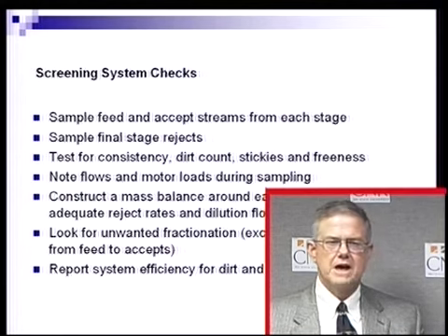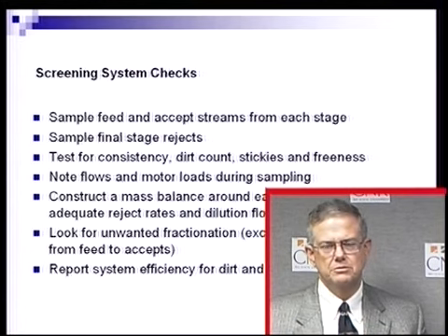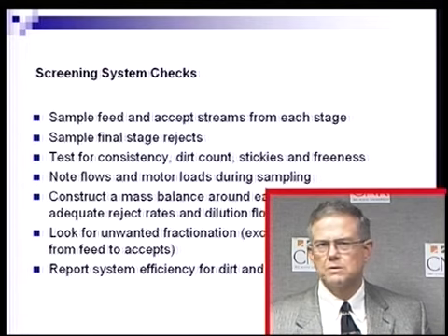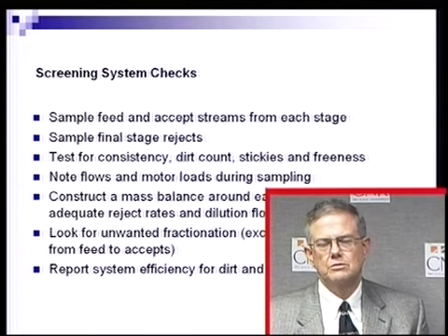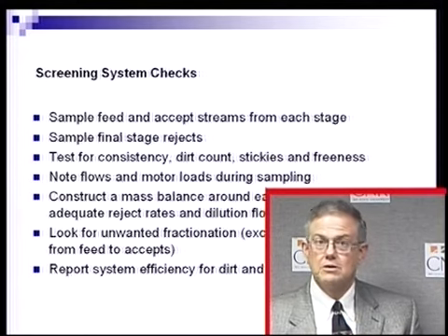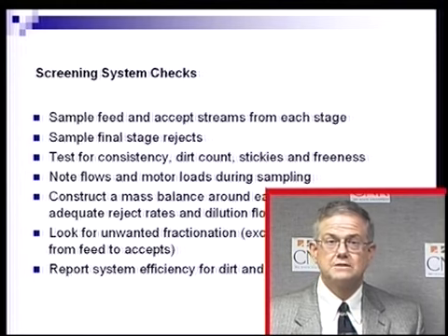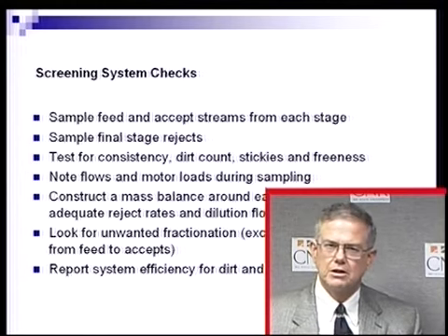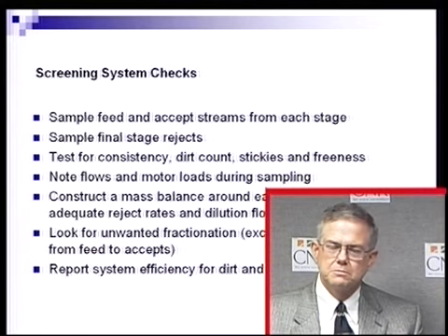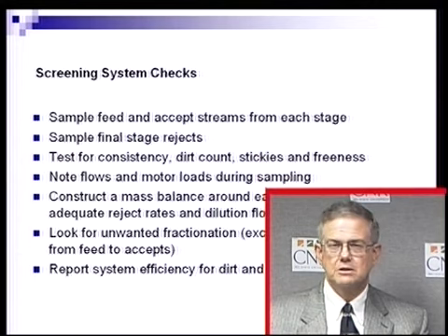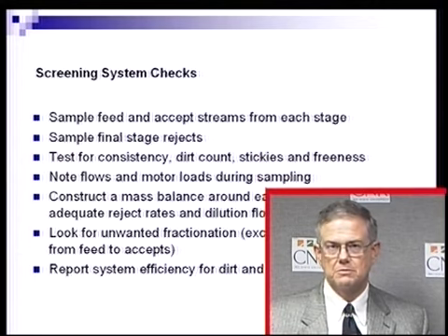We'll construct a mass balance, very simple with the tools that we have available to us today, to use an Excel spreadsheet, for instance, to simply enter in this data and do the calculations automatically so that we can see what our flow splits are, see what our reject rates are by mass and by volume, calculate our thickening factors, look at the loading in terms of how many tons per day per square meter are we putting through, what's our passing speed, how many cubic meters per second per square meter are we putting in.